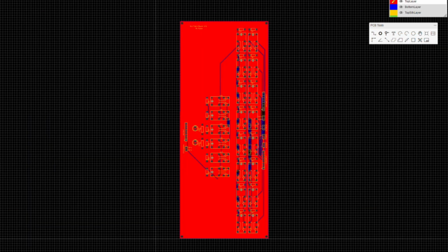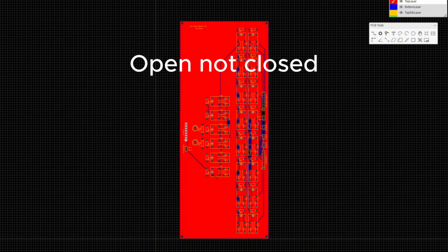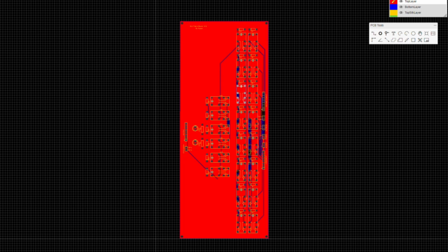So this is what ties together the arithmetic and the logic units, and it also takes care of the carry flag and 0 flag. On this board you have your input from the arithmetic board and the one from the logic board. By default, this will always output arithmetic when it's enabled, which will be this one. When this pin is on, it enables the output, and that works by these relays here having it go into the terminal here, and when you enable it, it puts power to all these relays, and it switches to the normally closed, and the normally open is attached to these, but it first goes through the 0 check.